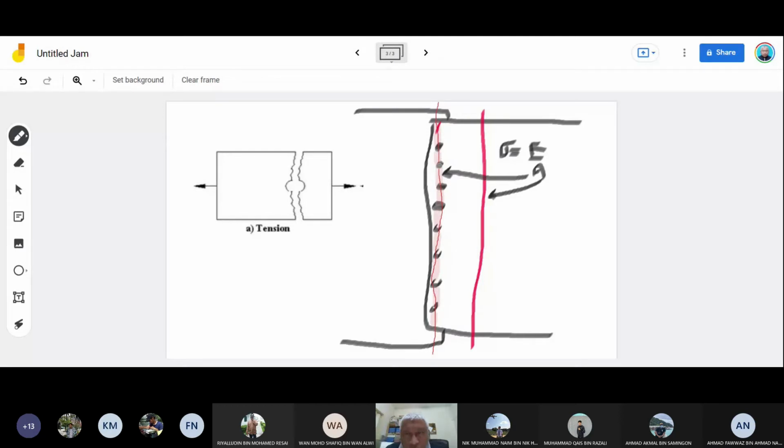So as the area becomes less, the force here remains. We don't change it, because if you design the aircraft, whatever you do, you design to that force, and the force remains. It will not change throughout the aircraft operation. Now, if the area becomes less, the stress becomes higher. If the stress is too high, this is the stress and strain curve.